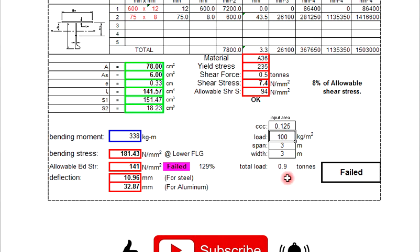But if you want to change to become smaller, you can use the 75. So this one is the uniform load, 25 kilogram per meter square. So if you want to use 100 kilogram per meter square, it carries 0.9 ton. So this size you cannot use, so you have to make it bigger.